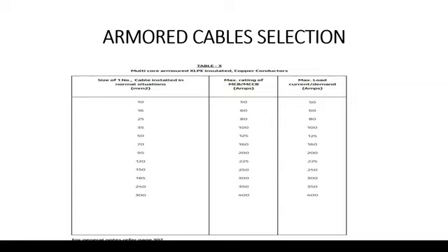If I have a motor load which doesn't have any control panel, I would use a 3-core cable. If I have a load that is a DB or a control panel or any type of load that requires a neutral, I would use a 4-core cable. So either 2-core, 3-core, or 4-core, again depending on the application, the load type and the starter type as well. So that's it in brief regarding the cable types and the cable selections.